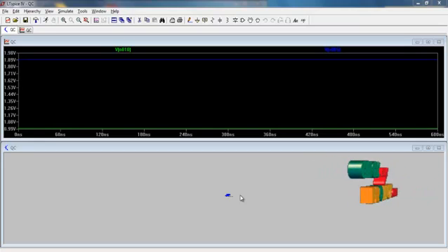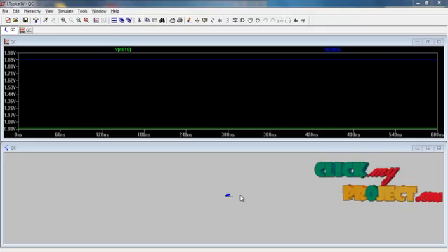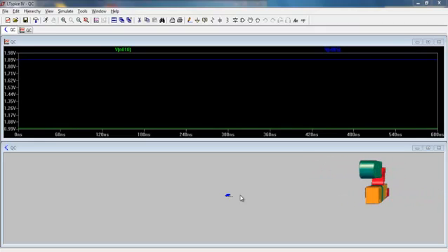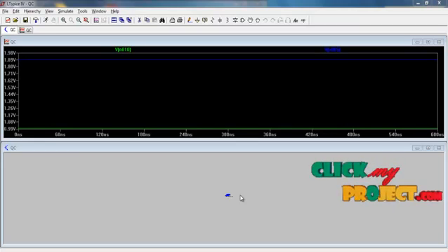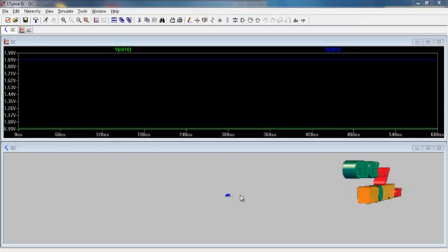Both quasi-circulator and bridge T network utilize the inherent non-reciprocity of transistors to suppress S31, and small values of S13 are also assumed, and therefore P1 and P3 are mutually isolated. The capacitors C3, C4 and the feedback resistor are the basic elements of the BTN. The cascode topology consists of the common source CS stage and common gate stage for improving the isolation of S12, which can also be regarded as the external amplifier.